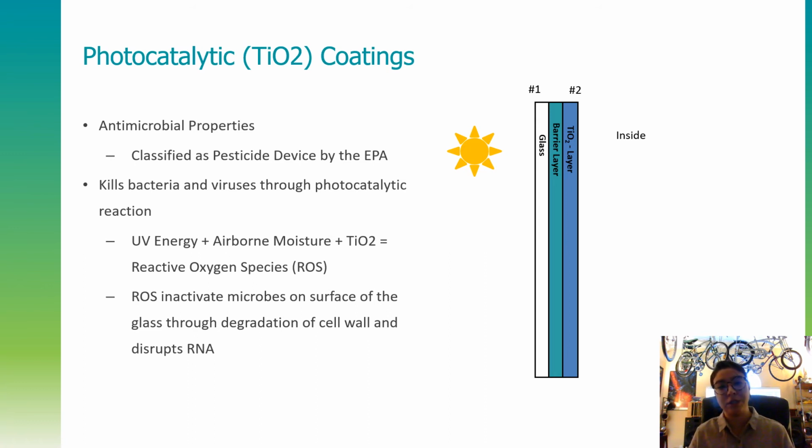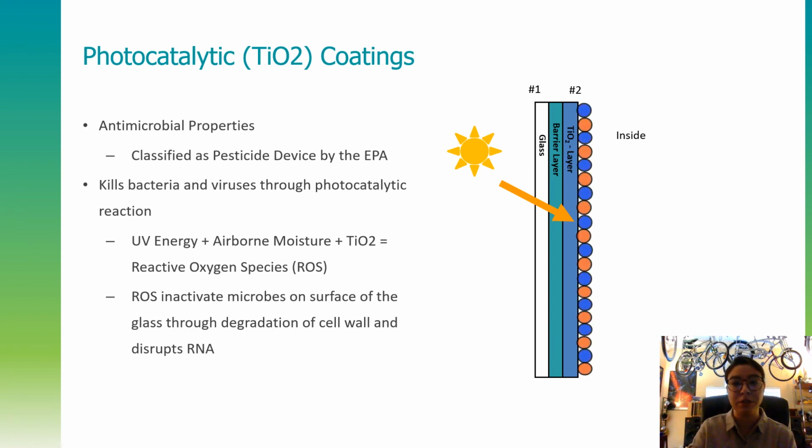What actually is occurring is the combination of a UV light, the titanium dioxide coating, and general airborne moisture, so really just the natural moisture that's already in the room. When you have this combination, they create reactive oxygen species on the surface of the glass, essentially hydroxide and oxygen molecules.